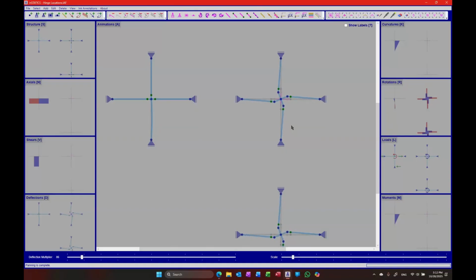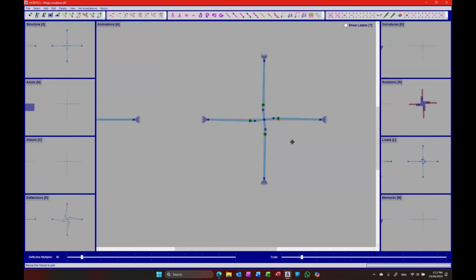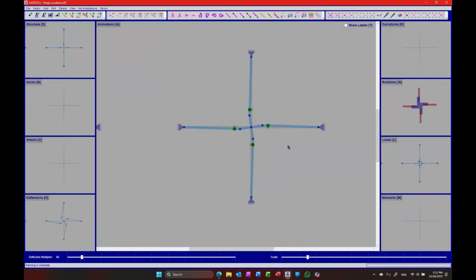Yeah, I mean, I always wonder this because whenever we use SAP or something, at an intersection at a joint, you would release the moment in every single element except for one. So is that basically the reason why, otherwise it creates its own mechanism? Exactly. So the joint itself becomes a mechanism. Sometimes SAP does some weird stuff.